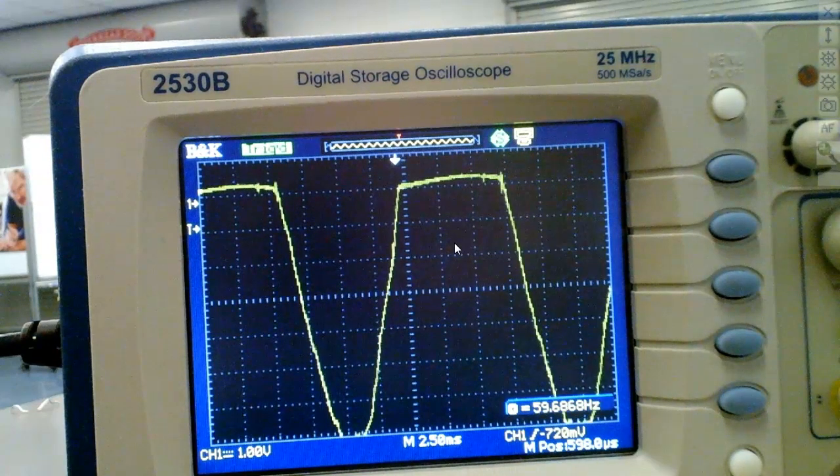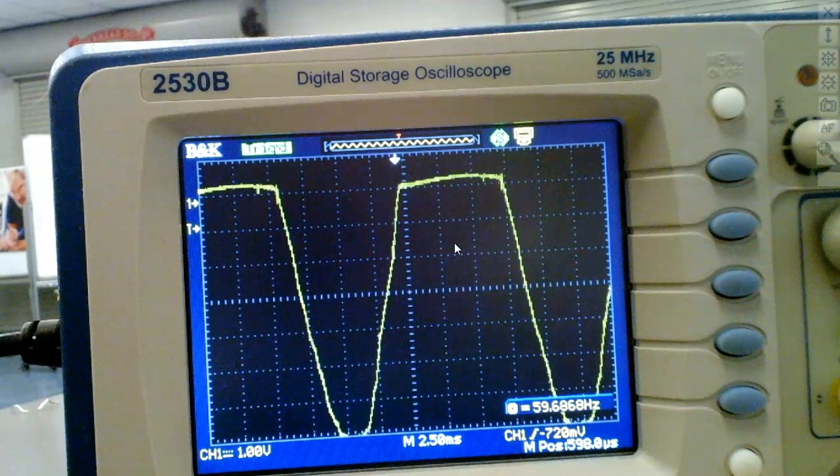And we use both of them, especially if I'm going to regenerate AC. So if I'm going to take DC and regenerate AC, then we're going to have to get a negative and positive voltage, right? To get AC. That's what your car radio's got in there, because you can't put DC across the speaker. If you put DC across the speaker, it'll burn the speaker up, burn your radio up too.